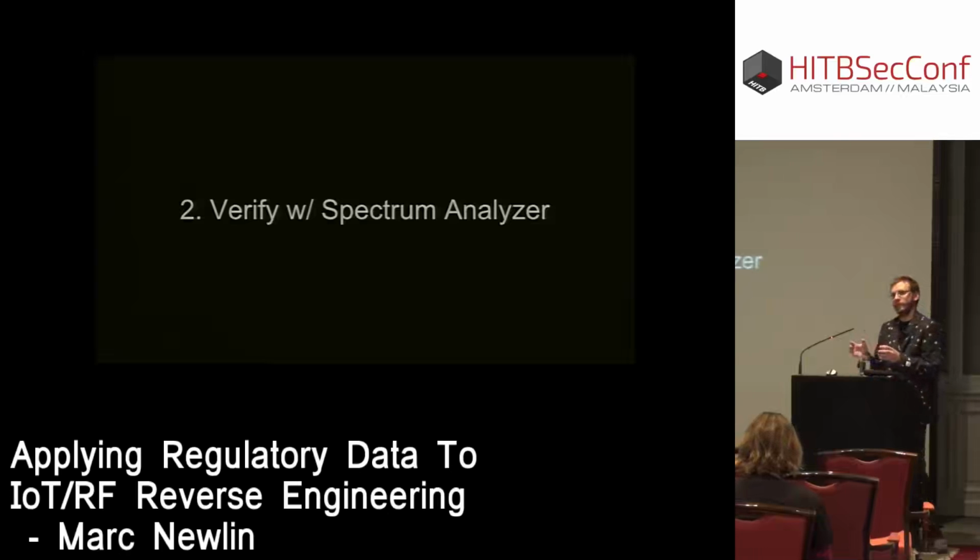So now that we have this information, we can have the device generate some traffic, in this case, moving it around or clicking the mouse button or whatever, and look at that with a spectrum analyzer using a software-defined radio. And with this, we can confirm whether or not the information that we have so far is accurate.